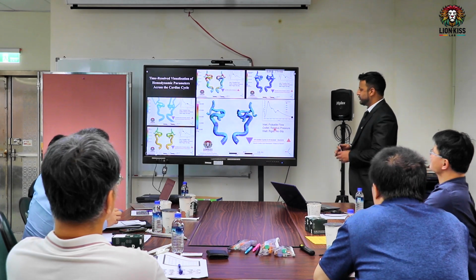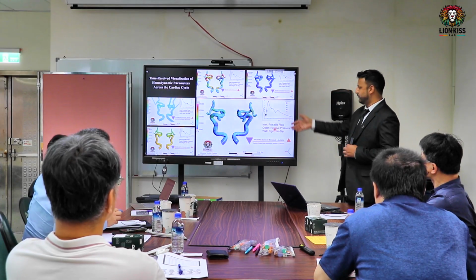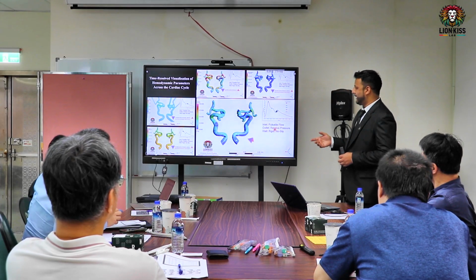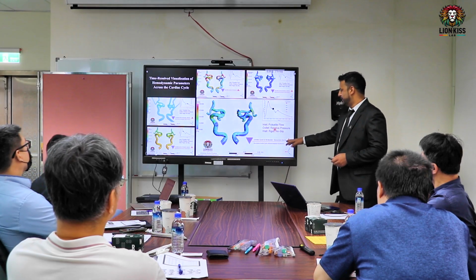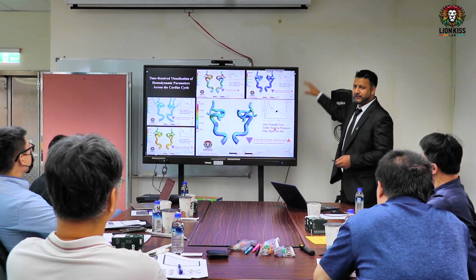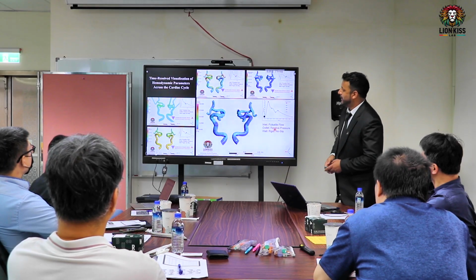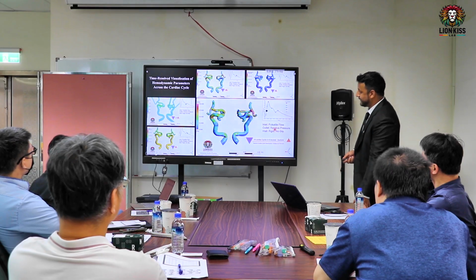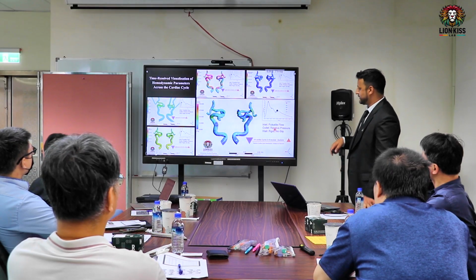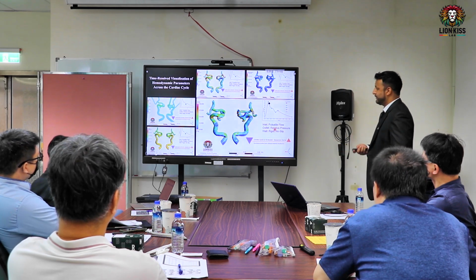Yeah, so here I show 10 cardiac cycles in 8 seconds, the effect of the pulsatile flow on the intracranial aneurysm, and after that I show the cardiac cycle in a 10 second slope, how it's affected by the pulsatile flow. In the same way, I show the pressure gradient, vorticity, velocity, and wall shear stress. So it's 10 cardiac cycles in 8 seconds and one cardiac cycle in 10 seconds.